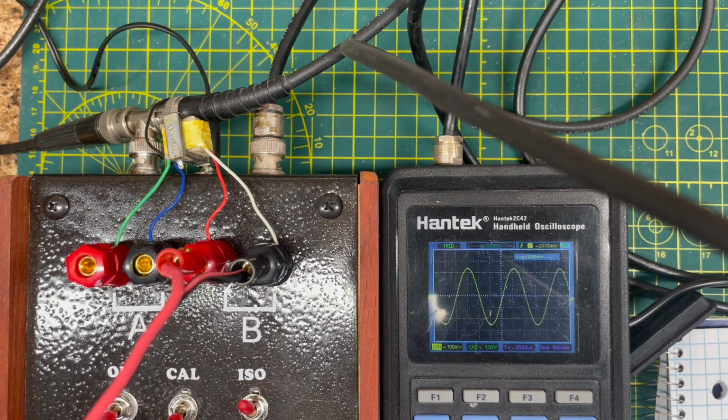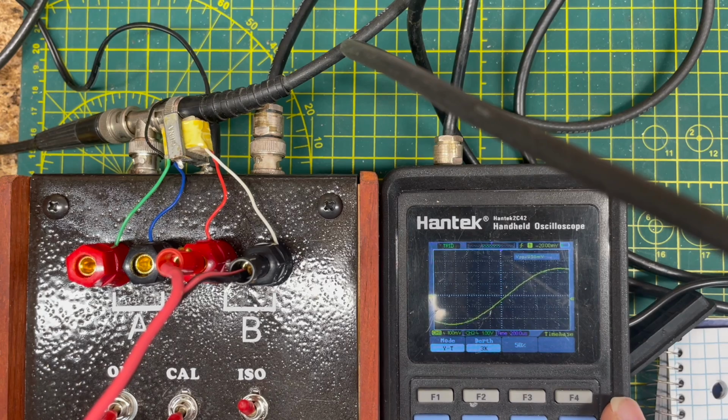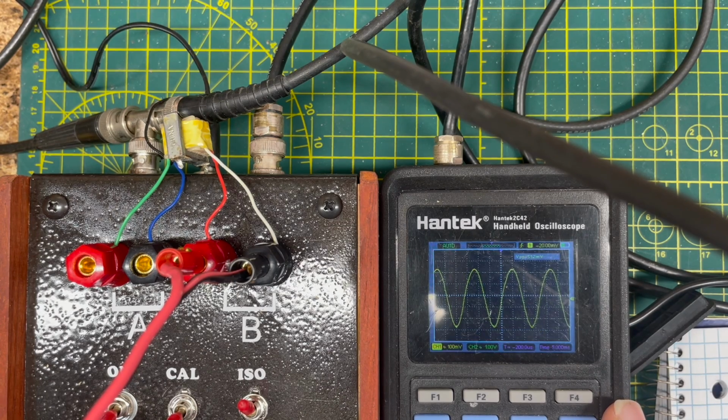Till that goes down to 350 millivolts. Right there you can see it starts distorting. So that's about the lowest bandwidth before you start getting distortion. And on our frequency generator, that's at 60 hertz. Now we're going to go the other way.